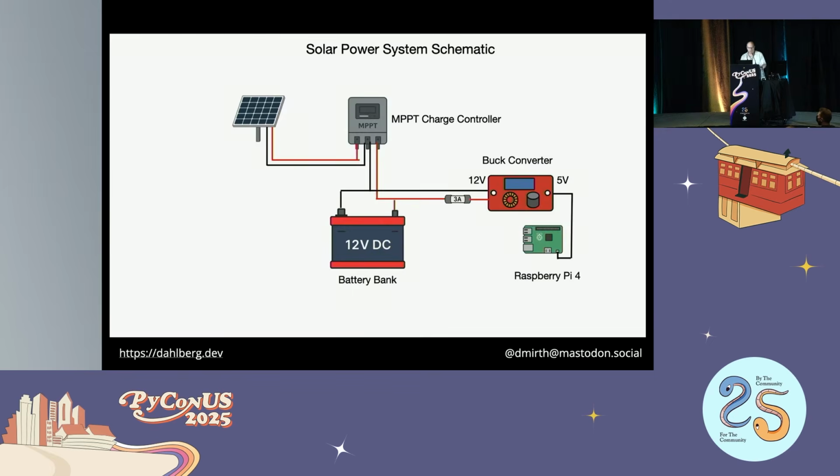In addition, setup of a solar power system requires a bit more than bringing the PV cables to the hive. The first necessary component is an MPPT, or maximum power point tracker, charge controller, which is an electronic DC to DC converter that optimizes the match between the solar panels and the battery bank. It converts a higher voltage DC output from the solar panels down to the lower voltage needed to charge the batteries. It is connected to a battery bank of deep cycle marine batteries.